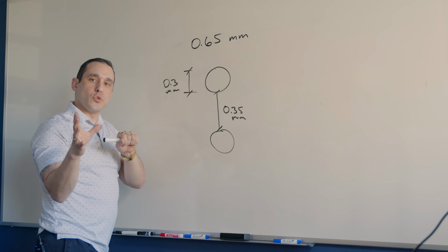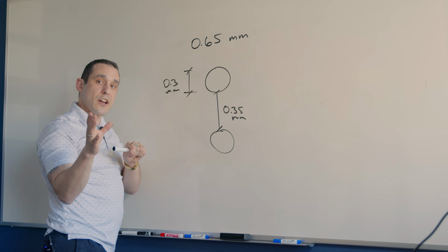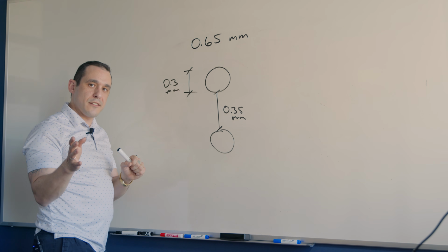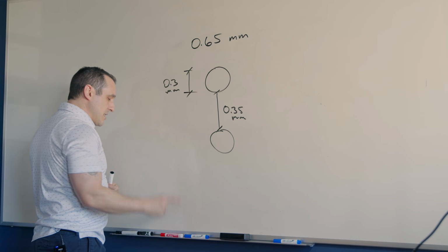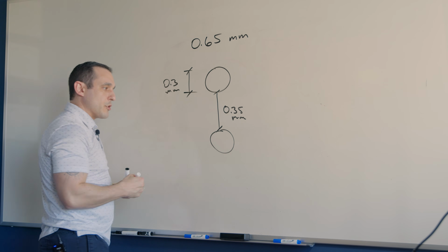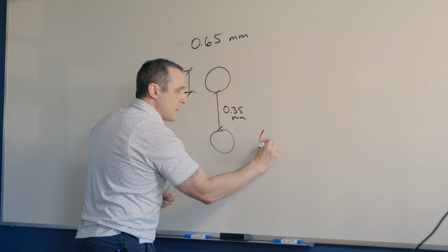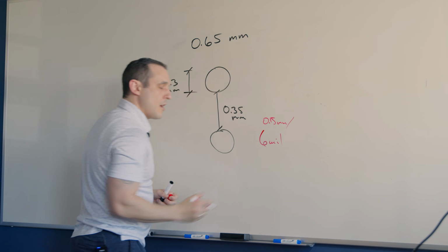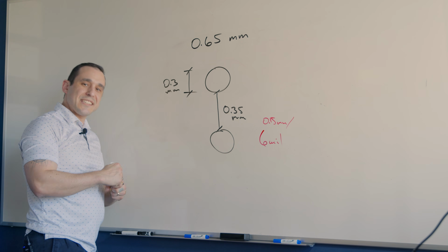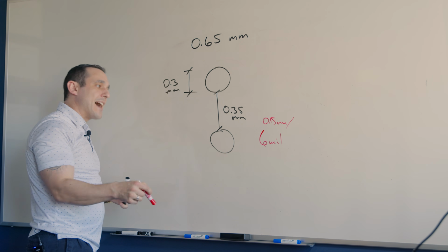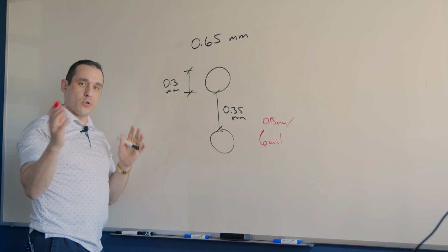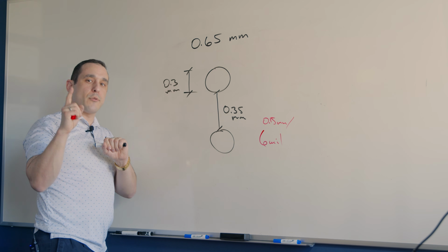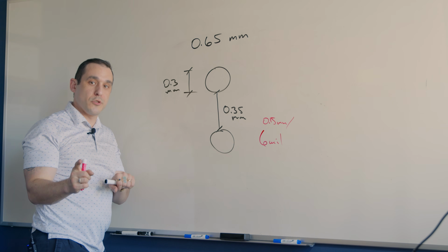Well, I'm going to have to ensure that I have enough annular ring around that drill in order to comply with IPC standards. So if I wanted to use even the smallest drill diameter of, let's say, a 6 mil drill or a 0.15 millimeter drill, that's going to require at least 8 mil of pad around that drill in order to meet IPC Class 2 standards, and that's assuming that our fabricator is operating at the highest producibility level.